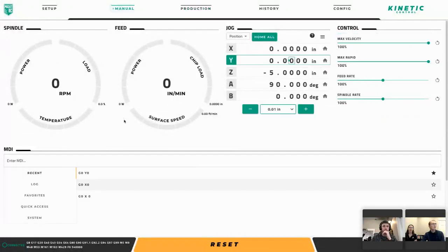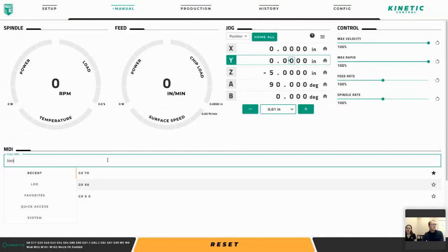let me just share my screen really quick. So in your code you can just put a debug message. So your current tool number is, so our active tool is number 3. So we could simply add that line to the tool change process, something like that. You can also add that to your post processor if you want to stick in some manual G-code. That debug message can be handy. Yeah, that's something that we could easily add in there, but haven't yet.